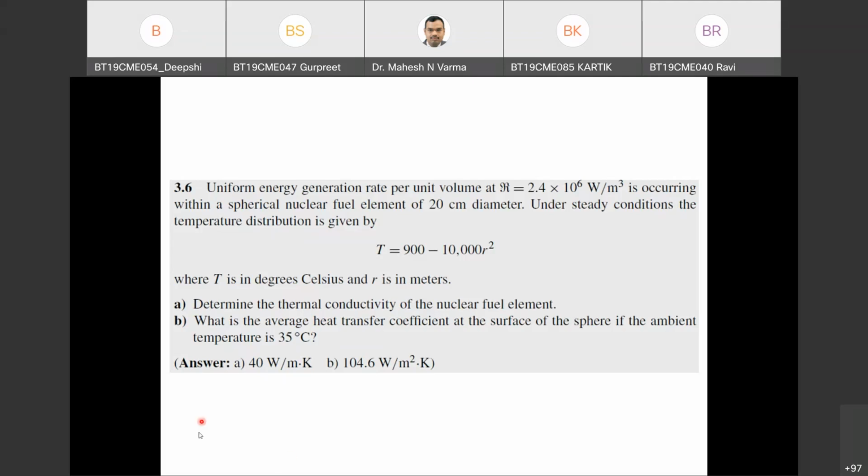Then here, heat transfer coefficient I need, h I need, delta T. From where I will get delta T? One temperature is given, so certainly the other temperature can be estimated here. Again, I have flux, so I can use Newton's law of cooling and get the heat transfer coefficient. So which equation can be used? Already you will have some outline idea from the given data itself.